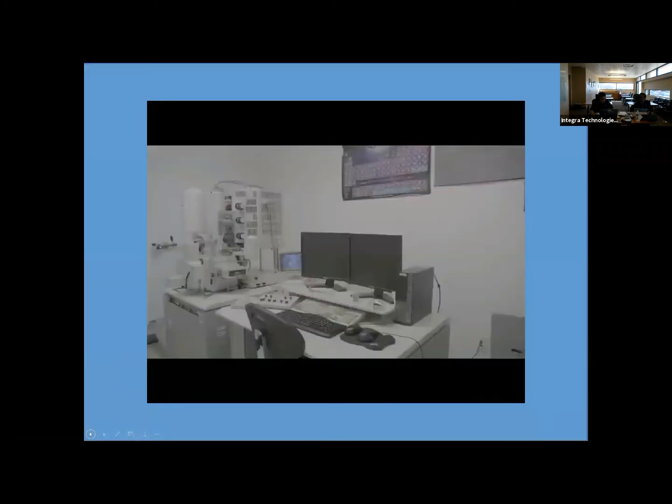Question, how do you remove the glassivation? Sure. So there's a couple of different techniques. MIL standard 883 gives a couple for when you're doing glassivation type testing. It depends on the type of glassivation applied. So you can have a nitride. You can have different types of glassivation, and you'll want to use a different type of etch. I would suggest looking in 883 test method 2021, I believe, for glassivation.